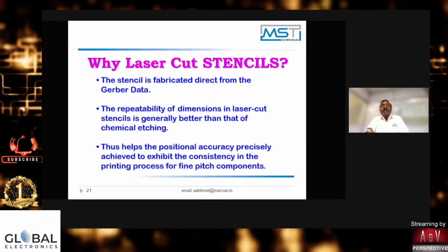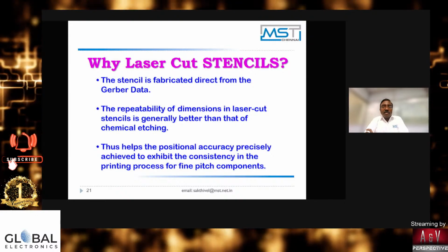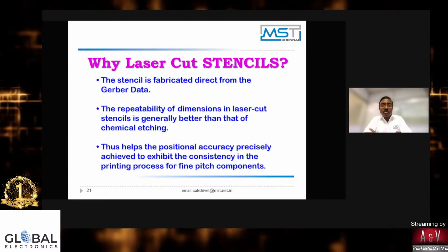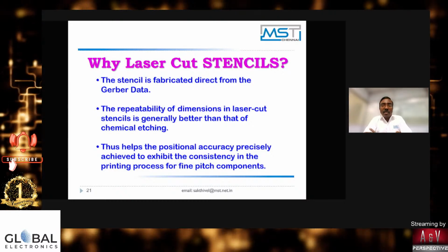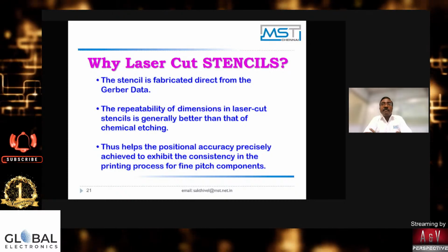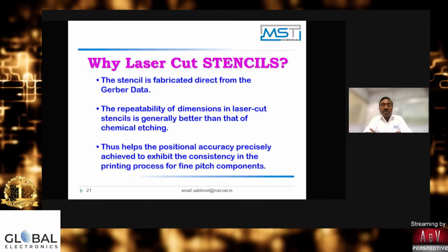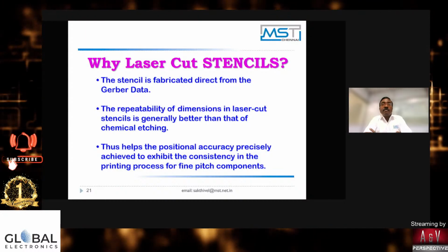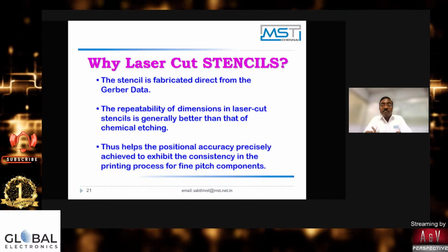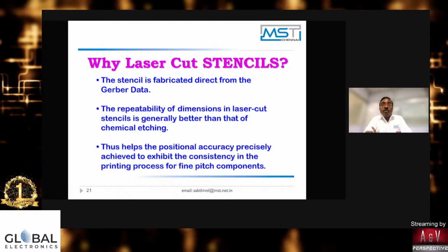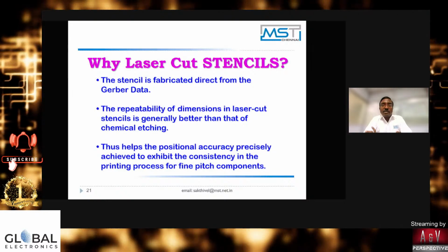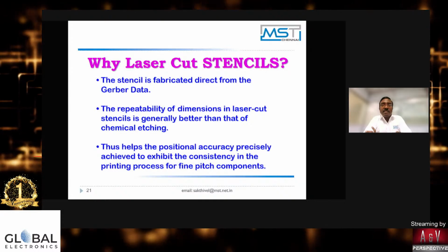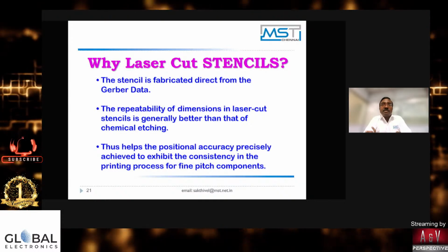Again, there are many variants of materials. We have usually been using stainless steel 304. Now, a higher version came. It's called fine grain stainless steel 304 or 301 for addressing fine element openings in the PCBs. So you need to select which model, which aperture opening is being used in the particular design. That will be predicted by the designers, specifically the experienced stencil designers.